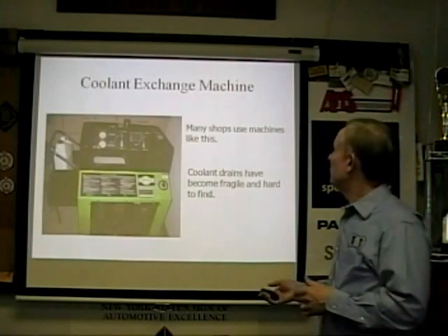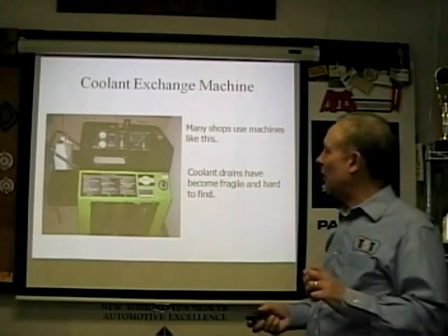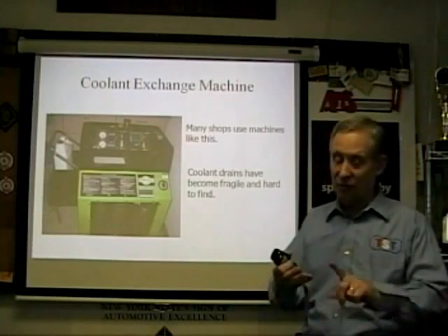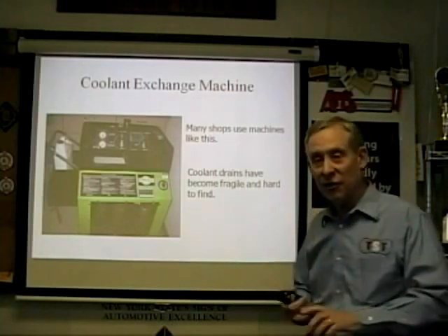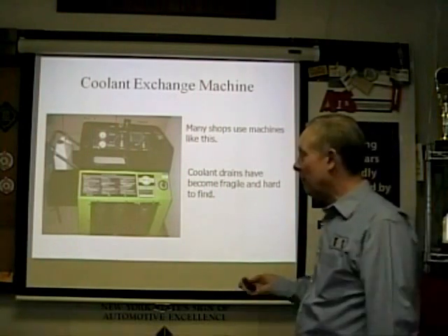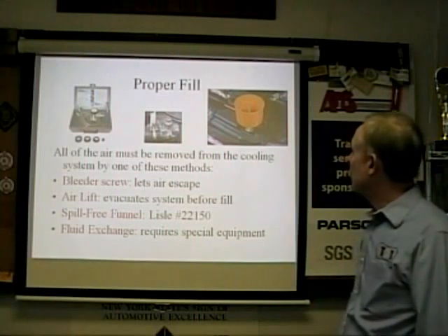All right. Many shops use machines. I'm unsure about how good this is. If you have one brand of coolant and you're very careful and you keep it clean, I suppose you can get away with it. As soon as you start mixing, all bets are off. Drain your machine out. You've got to watch that stuff.